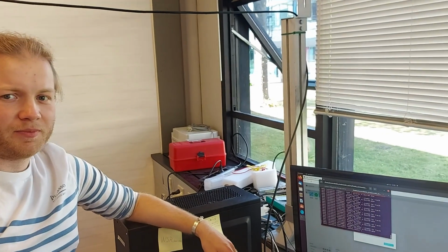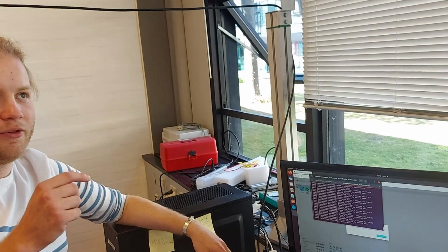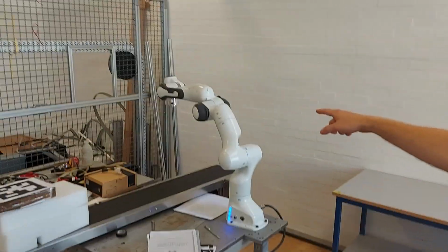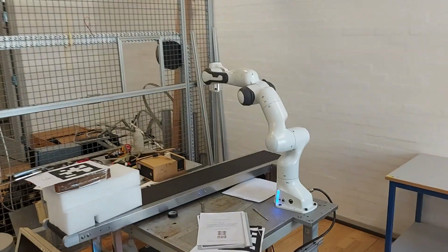in the node right before, I think it's in the prediction selector, I determine if... because everything is happening in the coordinate system of the robot arm space, I can say if I see that the ArUco tag's distance from the base is further away than what the robot arm can reach, then instead of passing on the detected coordinate, it will pass on some default coordinate, the one that it's going to right now, to a safe-ish location.